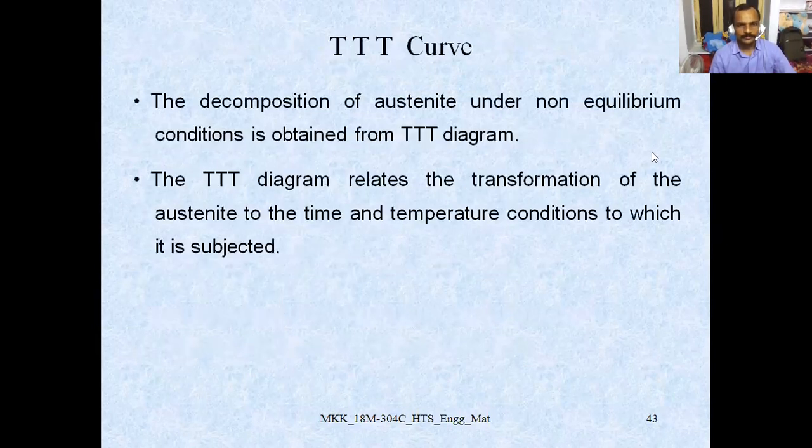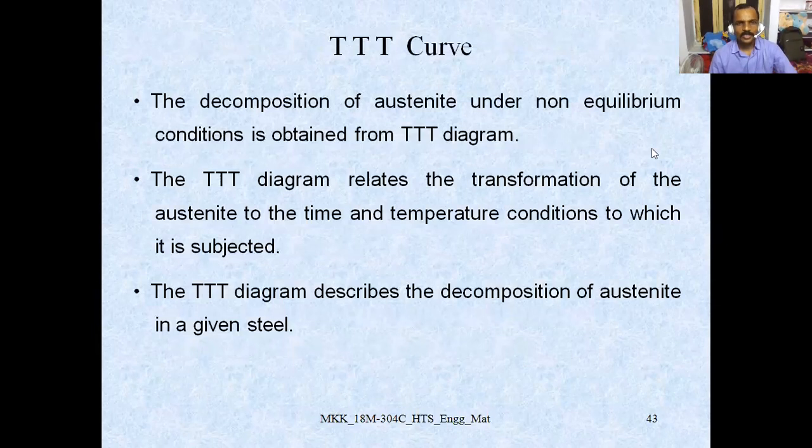Till now we have studied the tempering and hardening process. So now let us move to the curves, which are very important concerning engineering materials. The first one is the TTT curve. The triple T curve, the full form is temperature, time and transformation curve. So temperature, time and transformation curve. At a given temperature and time, the transformation from one phase to another phase occurs.